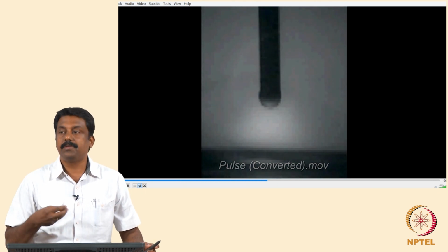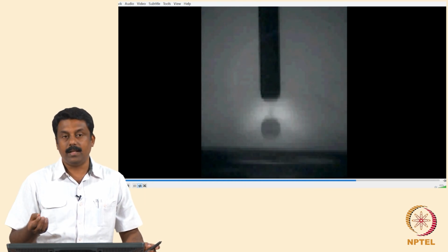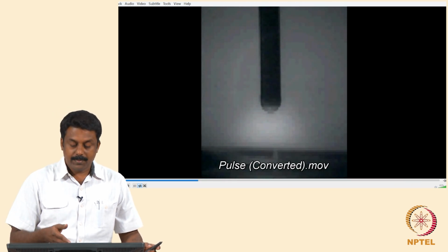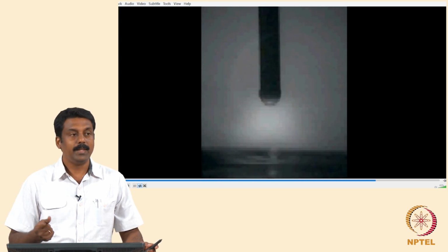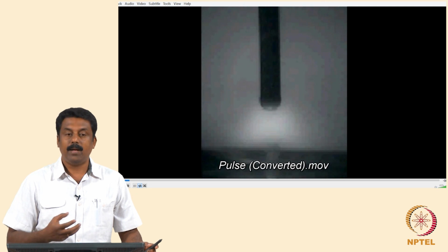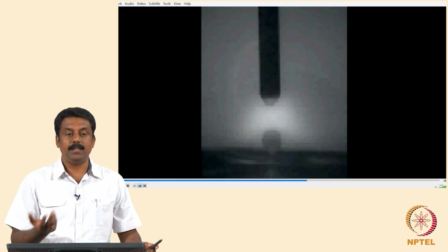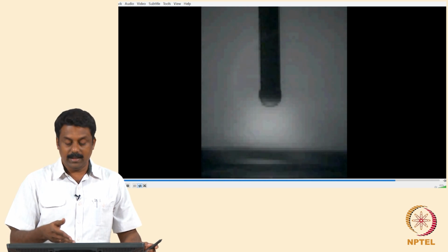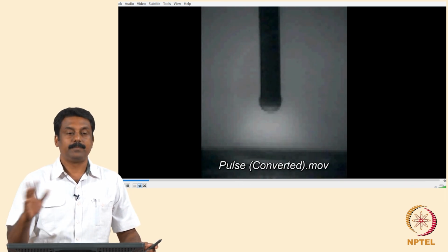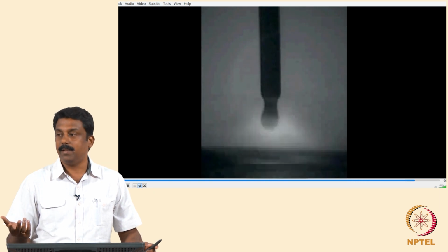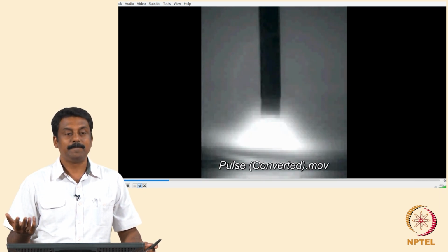So we will have to carefully choose the IP and TP and similarly the background current, which will depend on the characteristics of the melting wire, the composition, as well as the shielding gas that you use, because that will determine the amount of heat that is transferred to the tip to melt it, is it not. Melting rate is determined again by the heat in the electrode, the heat supplied from the arc to the electrode, right. And if it is an anode, you have 2 other parameters, right. What are the parameters?